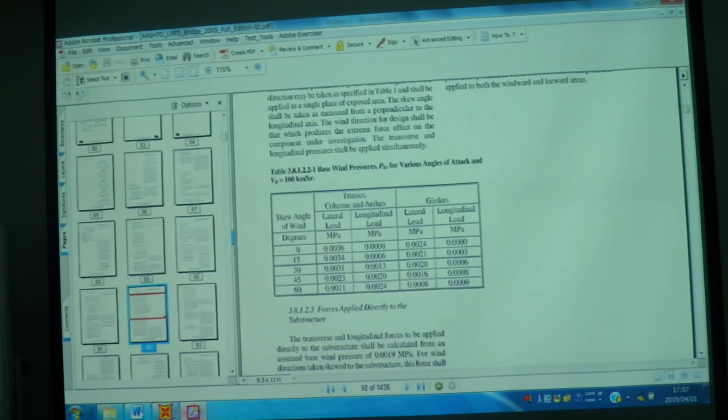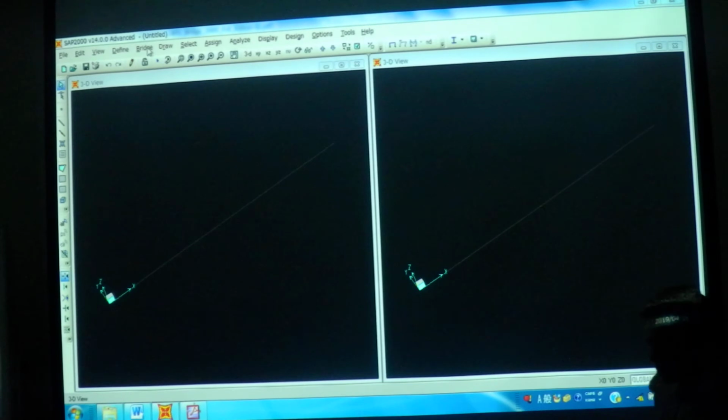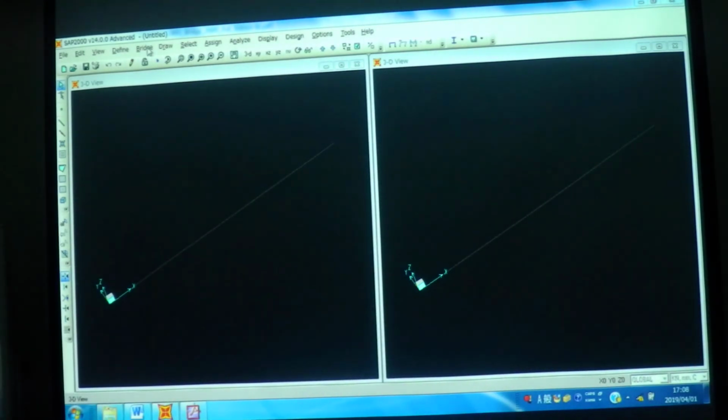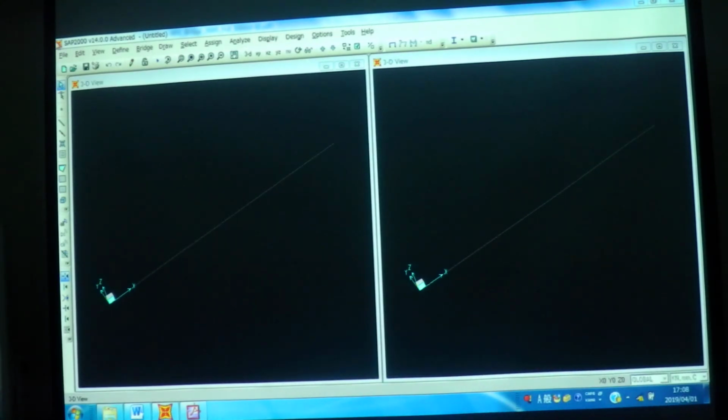Okay, and in this model, do you want to consider the HL93 truck or the same HS20 which we have included? For example, again, in this model I give you two choices. Number one, apply the truck load separate and lane load separate, or define it as an HL93 truck and lane load together. Which way would you prefer? HL93, the easiest one. Okay, no problem.